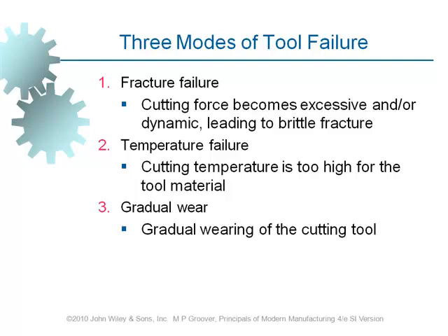Making use of coolant, yes, would do the same job. And what else? Lowering the feed rate, again. And the other possibility, if it is possible, is to make use of a different type of cutting tool which has a higher grade of material, which is still hard enough at that elevated temperature.